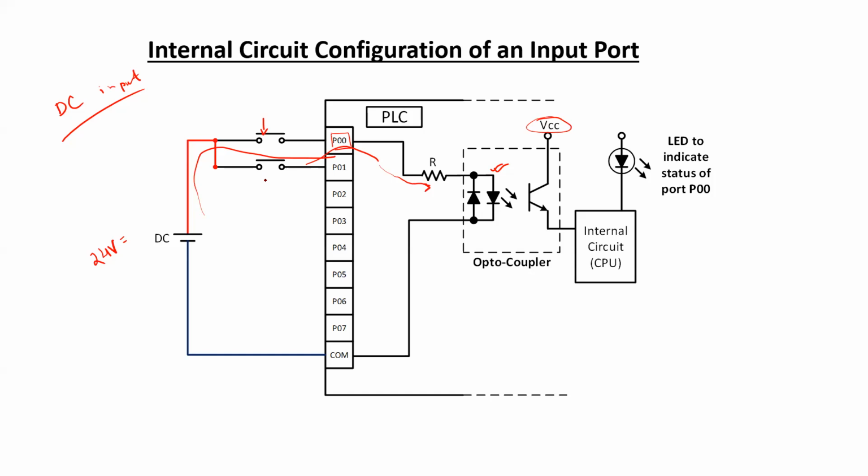So the input switches or sensors that can handle up to 24 volts DC source can be connected as the input devices for this PLC that we have in our hardware lab. However, the 24 volt supply is normally way more than the rated voltage of the internal circuits or the CPU or the microprocessor, because maybe the microprocessor needs only 5 volts to operate.